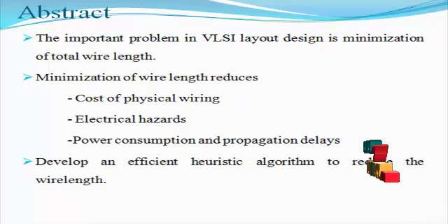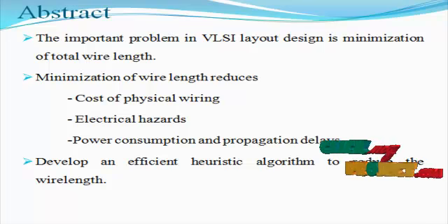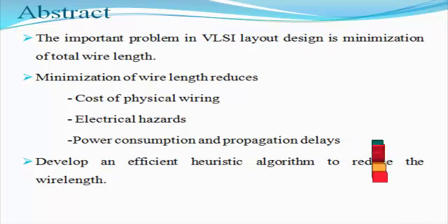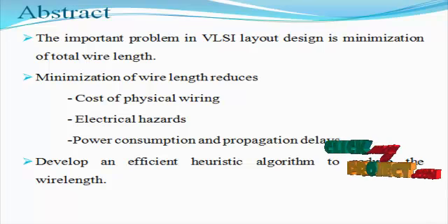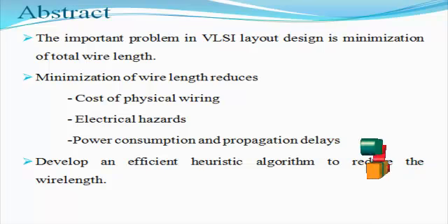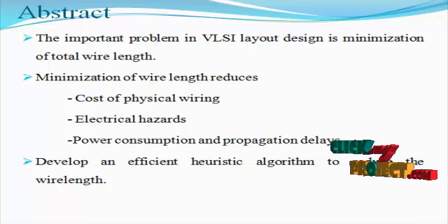Terminals are assigned integer numbers, and terminals with the same number are to be electrically connected and are called a net. A channel is usually specified by the netlist or channel specification. If a net contains only two terminals, it is called a two-terminal net. A net containing more than two terminals is called a multi-terminal net. The span between the leftmost and rightmost columns of the net is called the interval of the net.